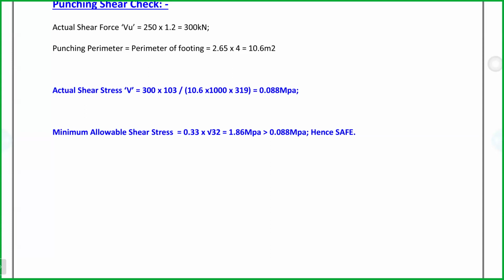At the end of this, we got the dimensions of the beam or the slab, but not the spacing. Check this out. Now see, in this we got the Vus, which is shear, and then we have a formula to check, and we got the spacing as 144 and so forth.